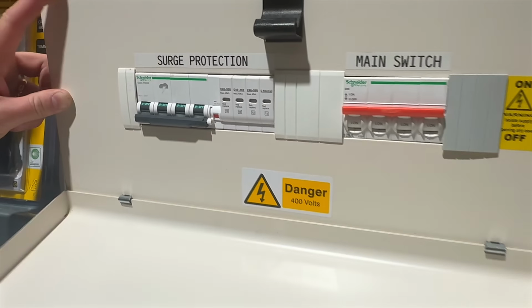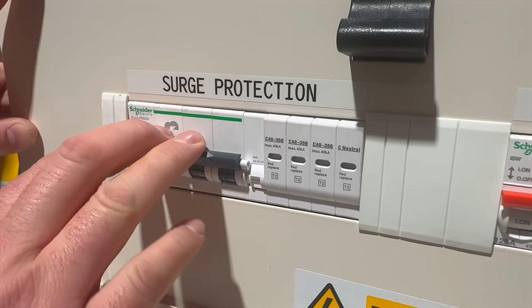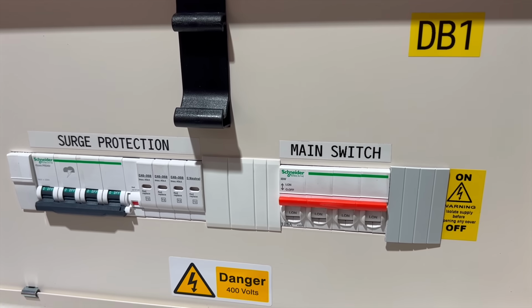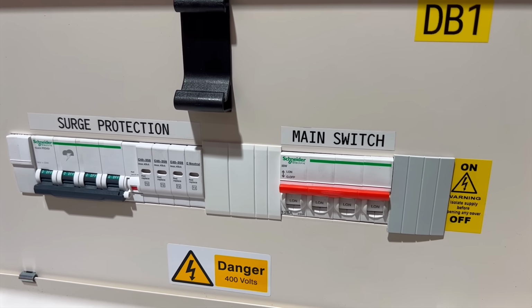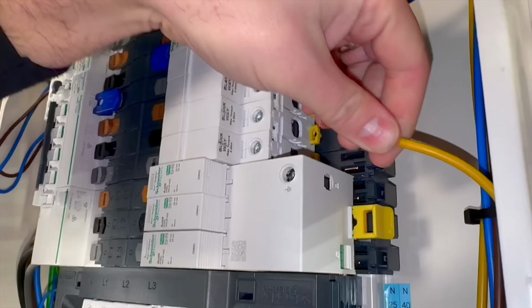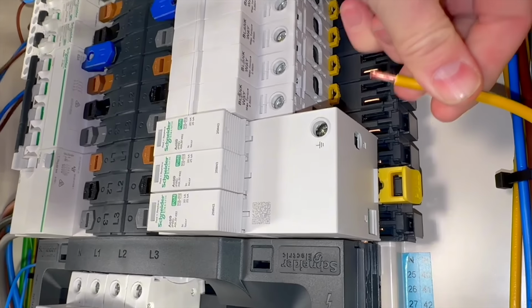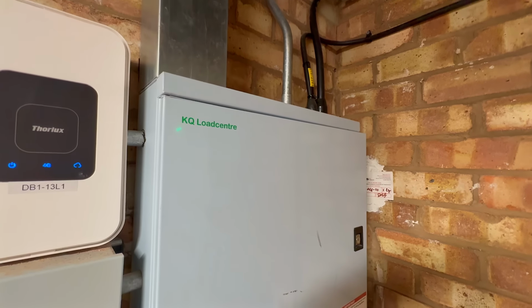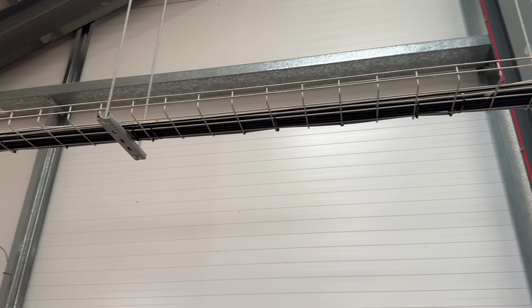In a traditional staged installation, a type 2 device may be installed at the origin and a separate type 3 device fitted closer to individual items of equipment. Those separate type 3 devices rely on a degree of impedance between themselves and the upstream device in order to share surge energy correctly. If they are installed too close electrically to the origin without sufficient conductor length between them, coordination may not behave as intended.